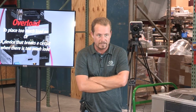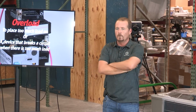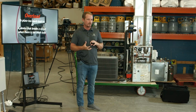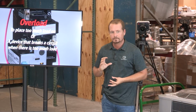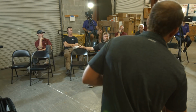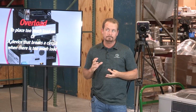An interesting thing about motors, though, is what happens to the electrical resistance in a motor. I'm going to dwell on this one for a second because it's really hard for people to get their head around. What happens to a motor's electrical resistance when its physical resistance is increased? So when the amount of force that the motor is working against is greater, what happens to the electrical resistance inside the motor? Anybody care to take that one? Max? What's that? Decrease. It decreases. Why does the electrical resistance in the motor decrease when the physical resistance against the motor increases? It's not spinning as fast.